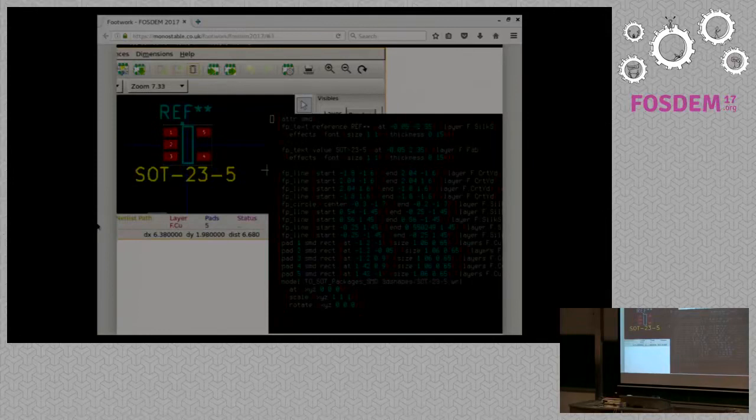Wouldn't it be useful if you had, for instance, databases with commonly known ICs and SMDs, where all the connections are known? With that database you could extrapolate those footprints with the language, and let KiCad automatically generate them from a database given by a manufacturer.